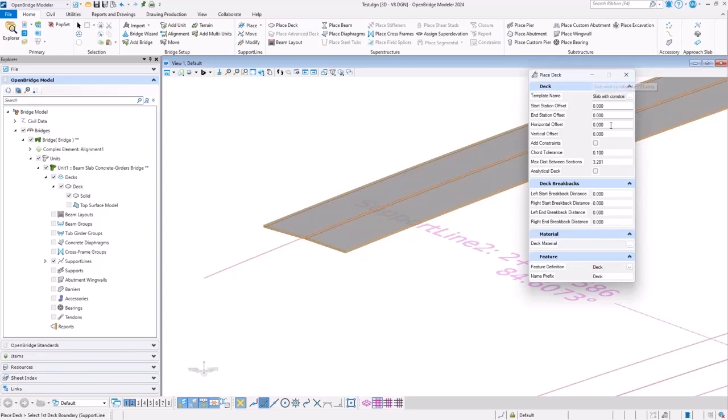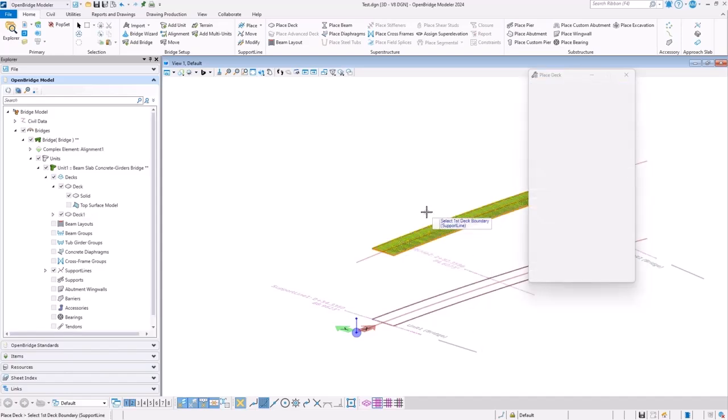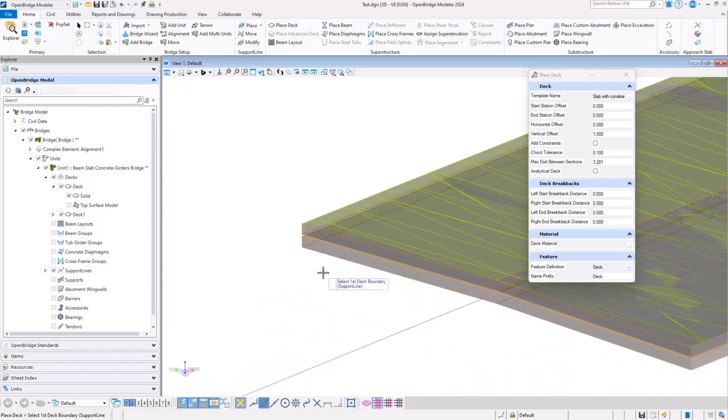So now it just automatically places the deck using the lowest deck being in place. So nothing to set up there. It just does it automatically. So giving you the advantage to specify sidewalks as we used to do all times. Now we do it with barriers, or just to specify different layers of the deck itself, like wearing surfaces. Okay, so that's it.